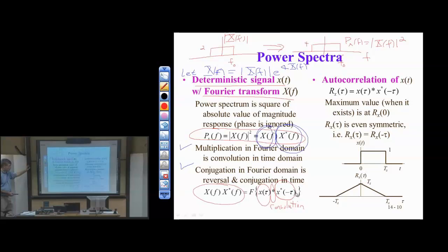Okay, so what's inside the curly braces for the Fourier transform is the autocorrelation function. Okay, so the autocorrelation function of x of t, we'll call this capital R sub x of tau, is just the x of t. We'll replace the little t with capital tau. So it's the little x of t convolved with the flipped version of itself. And then we have to conjugate the flipped version. For us, that doesn't do much. Our signals have generally been real valued. But in the case that x of t is complex valued, conjugation has a role to play.